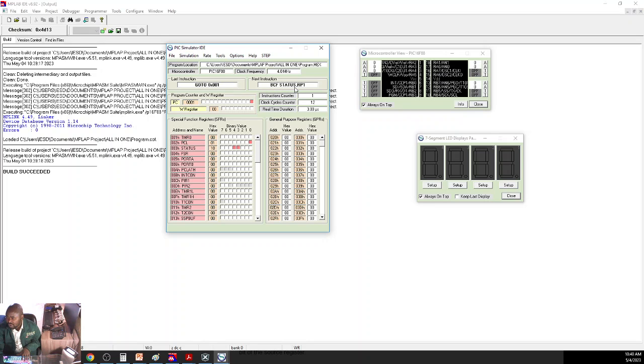From reset 00, go to start, where you go to bank 1. Bit clear STATUS RP1, bit set STATUS RP0, bank 1. Move 1 into the TRIS register. Only A0 is an analog input, the rest are digital. Move 80 into the ADCON1 register. Go to bank 0. Move value C1 into the ADCON0 register, selecting channel 0.